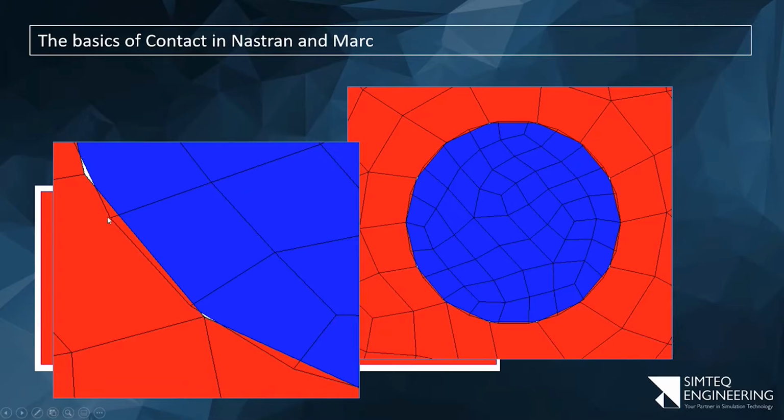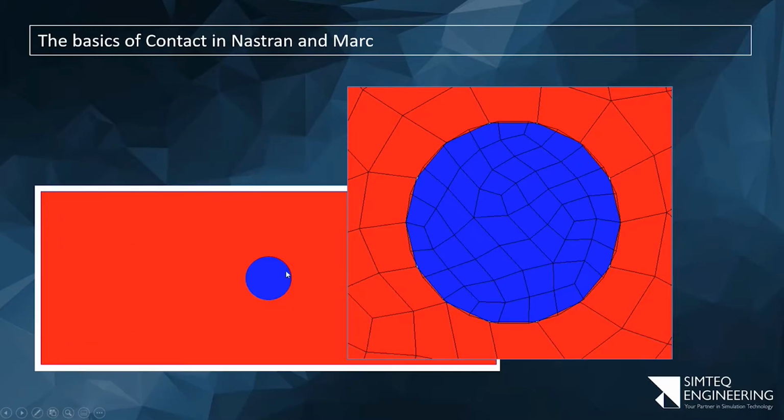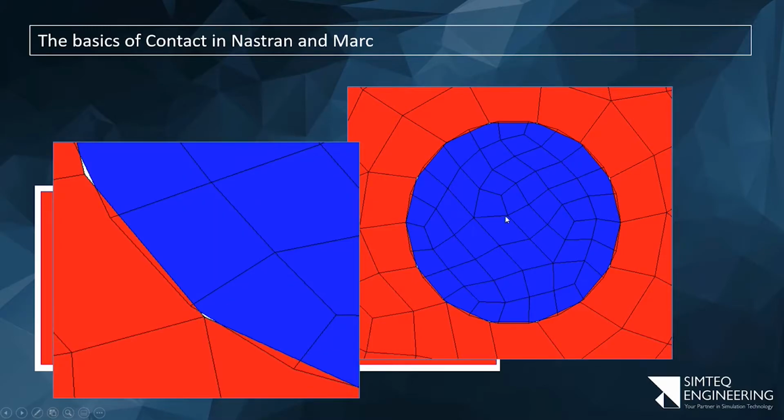The reason for that is we've got a discretized mesh of that perfectly smooth curve. So if I fit a curve through there, it will exactly look like the original circular section, in other words, that section over there. But I don't have the same number of nodes on the two, and even if I had, it may have been rotated a bit so that in some places it overlaps and some it doesn't. In some places there's an interference. So the solution to this would in theory be to mesh finer.